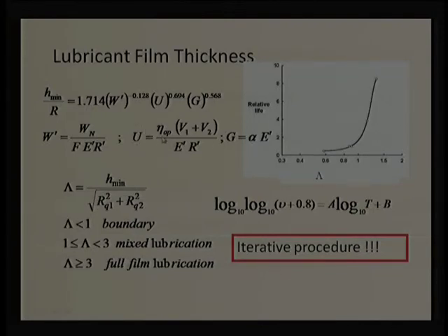As the temperature increases, this eta is going to change, and that can be predicted by a number of relations. We discussed two common relations from the literature: one is Walther's relation, the other is Vogel's relation.